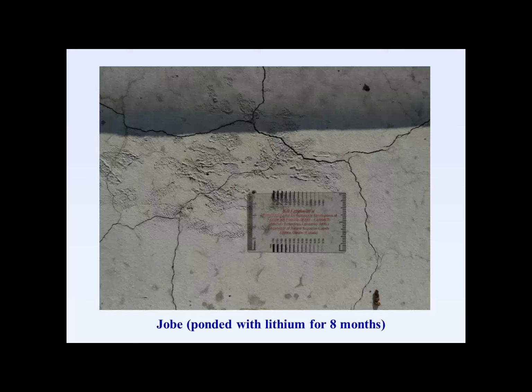Okay, next, this is a three-part question. What was the long-term performance of the externally restrained concrete? Is the process not capable of inducing stresses that can cause local damage? And if the structure is a column, is it not already restrained? Oh, good questions. Let me take the third part of that first. A column itself is restrained internally through the reinforcement, and oftentimes that internal reinforcement is enough to confine the ASR that's within that caged region itself.